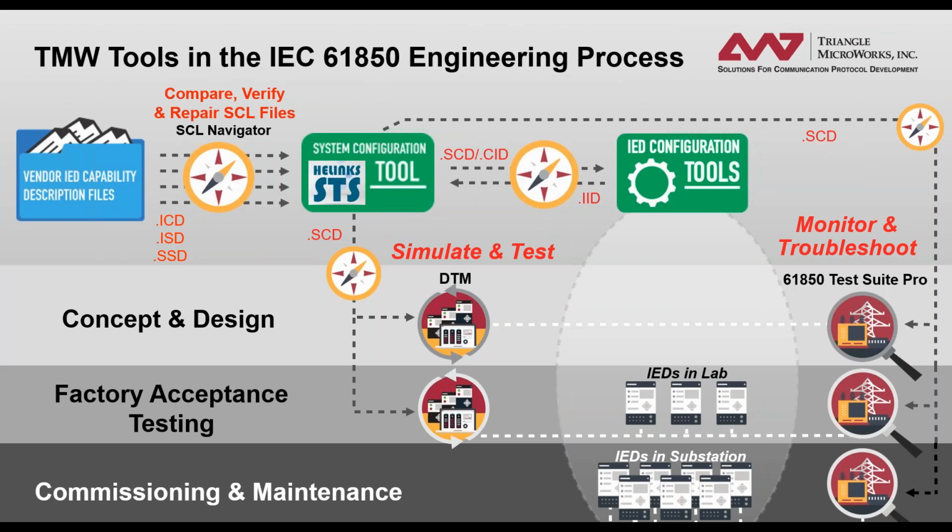If something has changed, Navigator allows us to figure out the differences, but we need to go back to the system tool to have the right file there. So the system tool, when importing an updated ICD file for an IED it has already imported earlier, will do a merge. I understood the question to be about doing a difference between revisions of an ICD file. Maybe I misunderstood.